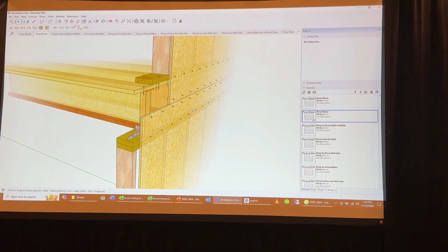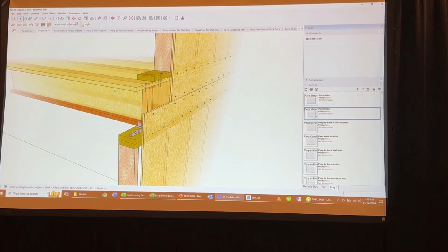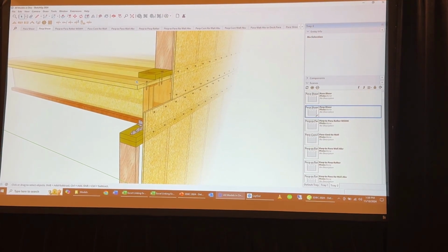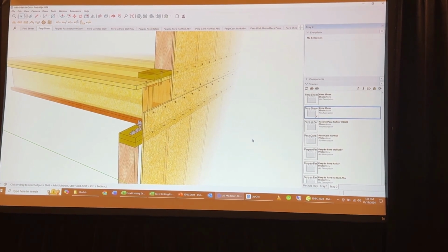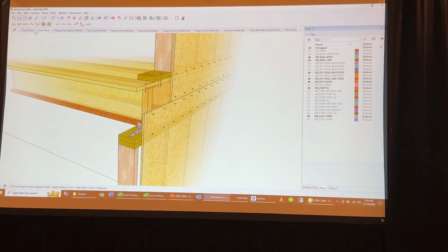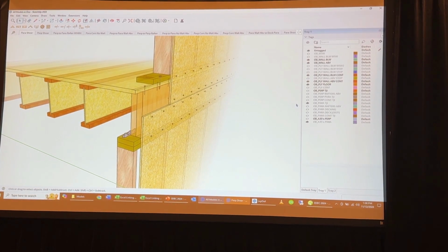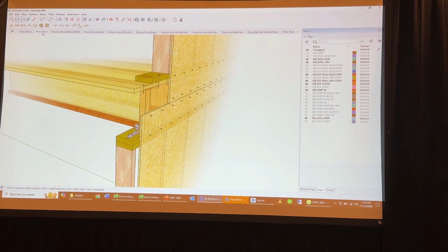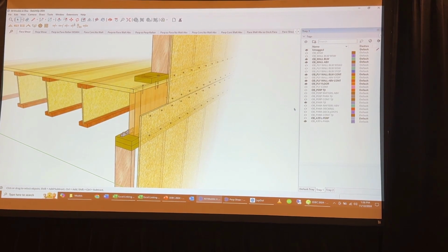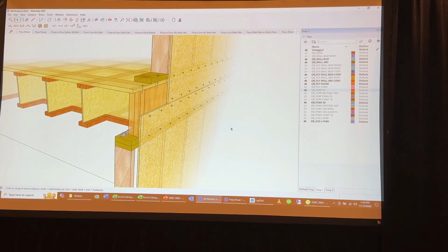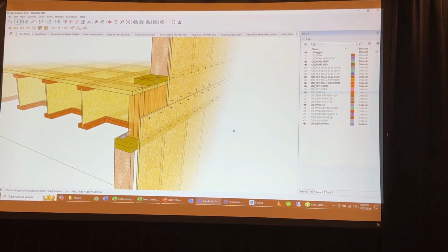So what we have here, I'll skip half a step, it's not that big a deal, is we're actually reusing the geometry as best we can, the components, the groups, and just updating our scenes. If we take a look at our tags, I'll probably call those layers a couple times, it's no big deal, we watch what's turning on and off here, right? I'm reusing geometry. That's limiting the size of our layout file.